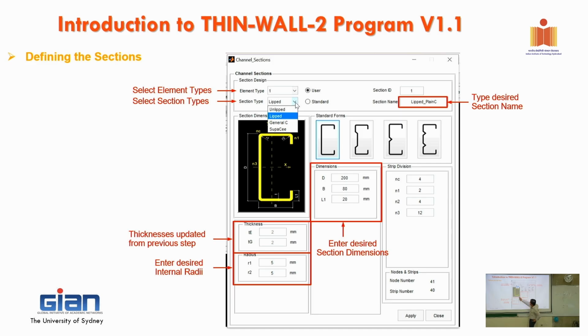And remember, look carefully at the figure in here, because the figure may be showing you the overall dimension. In the final shape, later on, the coordinates will be back-calculated to the center line dimension. So you need to look at the figure. This looks like it's overall, so you just input the overall section, not the center line.